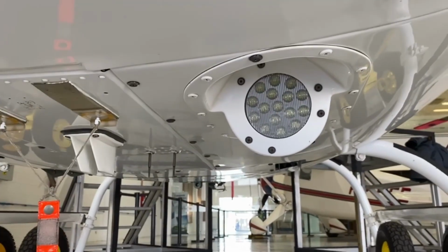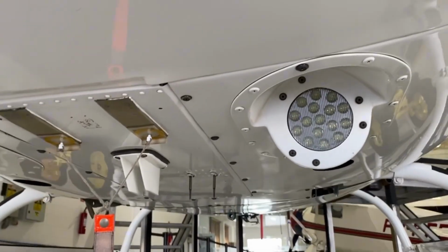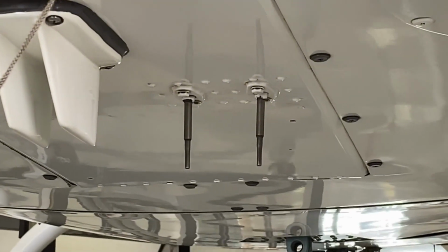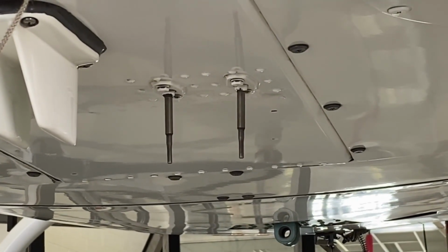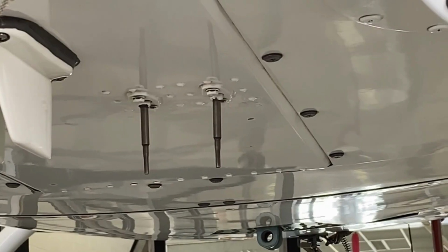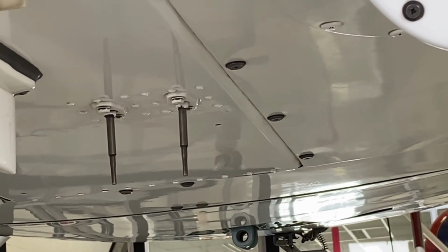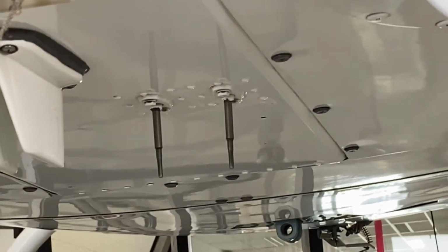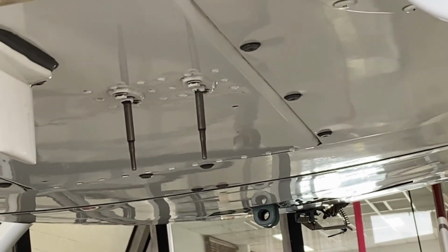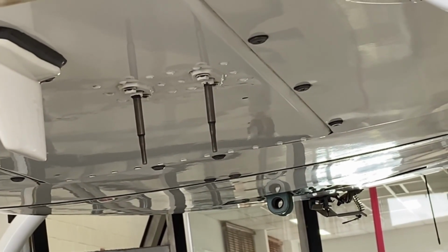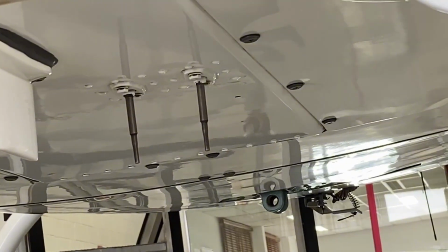Guys, we're here at the bottom part of the helicopter, the belly. And those 2 sensors you see here, those 2 antennas are temperature sensors. One is for the FADEC and the other for the VMD. The FADEC receives information about the outside air temperature to process the fuel dosage through one of these sensors. Okay? This is yet another piece of information that goes to the FADEC system's decoder to manage the fuel dosage.